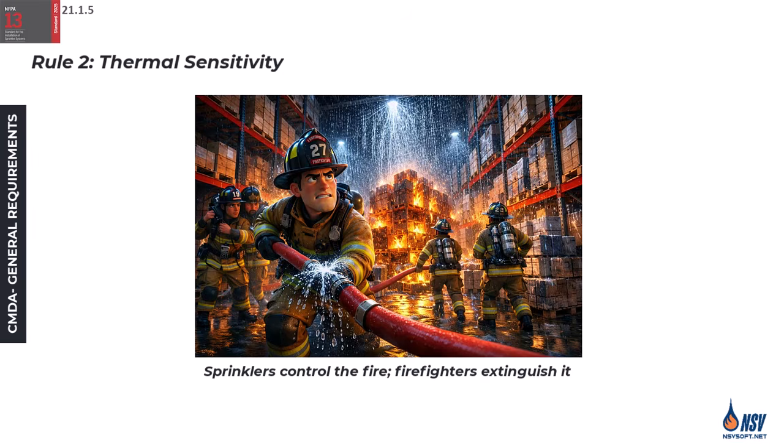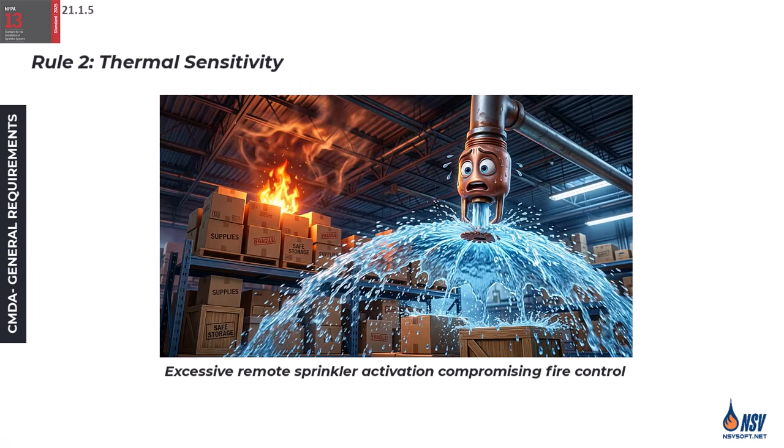Often, a sprinkler system will successfully establish control over a storage fire, but the fire will continue to burn and release a massive amount of heat until the fire department arrives for final extinguishment. Because quick response sprinklers are highly sensitive to heat, there is a real danger that this sustained heat release will trigger additional sprinklers far away from the actual fire.